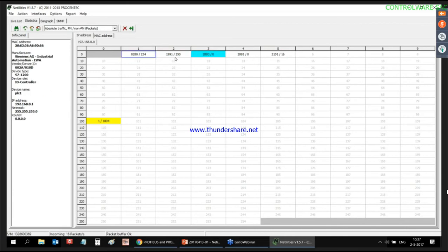And this device, and actually also this one, are sending also some non-Profinet data, which could be LLDP or ARP or SNMP, for example, some other protocols than Profinet. And you can also see that for the switch, it is mainly sending non-Profinet information because it has a web server. I have already opened the web browser, and that's why it is transferring probably some HTTP information.